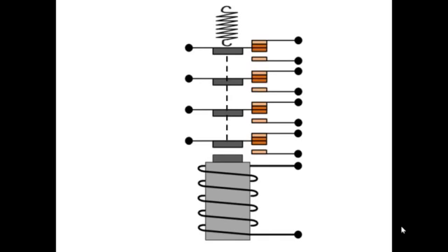They're all operated mechanically in synchrony, and we have a heavier switch, and we're going to need actually a heavier relay coil with more windings and more current, because remember that we have a heavier spring to pull back 4 Form C sets of contacts instead of 1. And we have to lift against gravity the 4 armatures. Actually, there's probably going to be 1 armature but 4 sets of contacts.